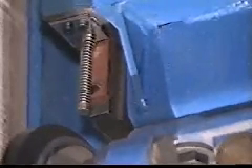There are safety devices on traction elevators that keep the car under control. One such device on a traction elevator is a large clamp called a safety. When activated or set, it anchors the car to the building by gripping the rails. The safety is activated by a device in the machine room called a governor. The governor monitors the car speed, and if the car overspeeds, the governor removes power to the elevator drive motor and brake.